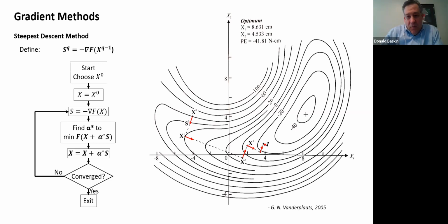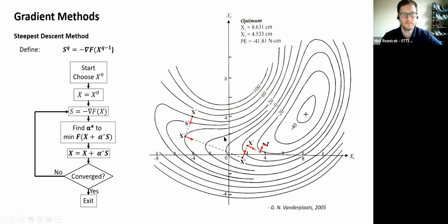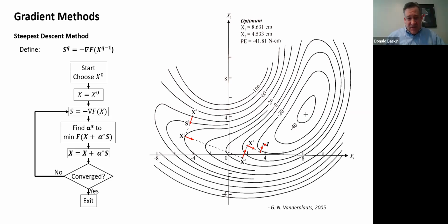And then the weight or the stiffness or the natural frequency, the strength, whatever it is, as you change the dimensions x1 and x2 together, gives you some function, some topography, some function of a curve. All you're doing is using a lot of cool mathematics that was developed in the 1600s or 1700s by guys like Bernoulli or Lagrange. You're using this fancy mathematics to find the lowest point in this case, or the highest point, whichever you're looking for, whether it's high strength or low weight.